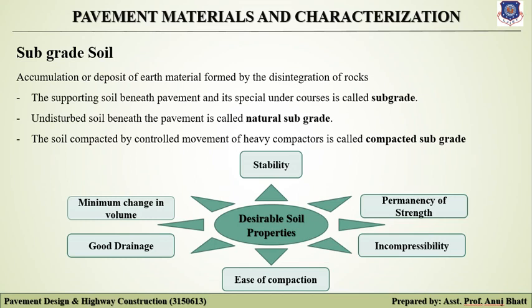Let's talk about stability. The resistance to permanent deformation under loads is called the stability of the pavement. There are a few factors which affect the pavement stability. First is vehicle and traffic. The next factor is moisture.